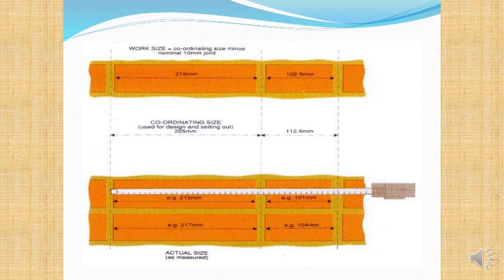Normally that gap will be maybe 10 millimeters, and therefore the coordinating size of the stretcher dimension goes up by 10 millimeters. So the coordinating size, the stretcher length, is 225 millimeters.